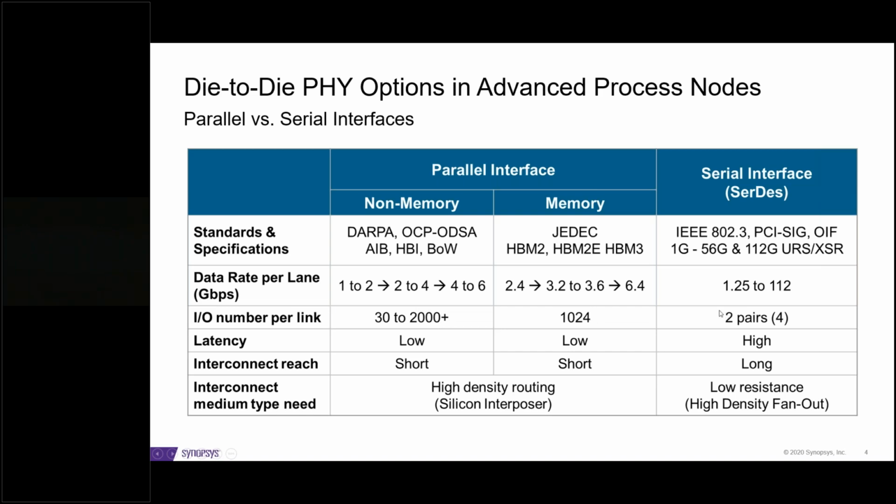Now, SerDes, as you pointed out, requires very few differential pairs. Pretty much, you could get almost the equivalent of the 1,000 wires of a parallel interface with 4 wires connected with the same throughput. Now, in the SerDes part, you need to go from a parallel interface, which is typically what your core is designed in, to a serial. Right. And then you communicate across the line, and then you convert back to parallel. That's the latency, conversion from parallel to serial.